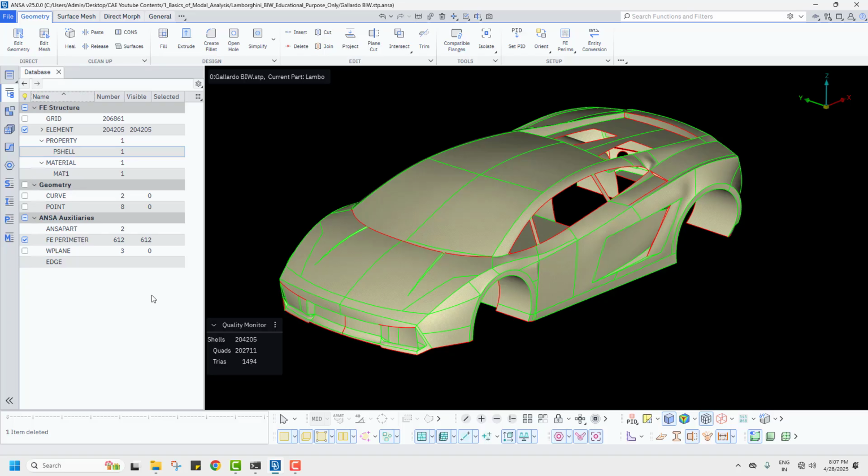From the 7th mode onwards you will get to know whether the assembly is perfect or not. If something is flying, it shows that the components are flying, or if a region is less stiff, it will show that this particular region vibrates a lot. The 7th, 8th, 9th and 10th modes will indicate the automotive component behavior, the torsion and the bending. The first should be torsion, and then the bending should come.